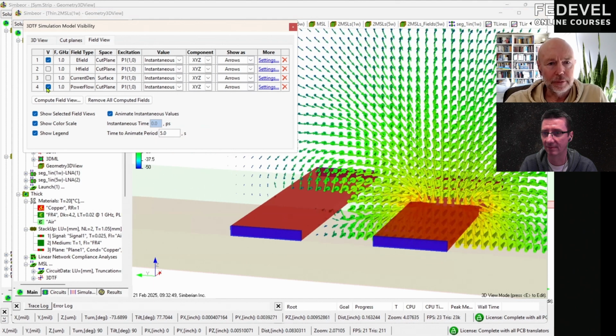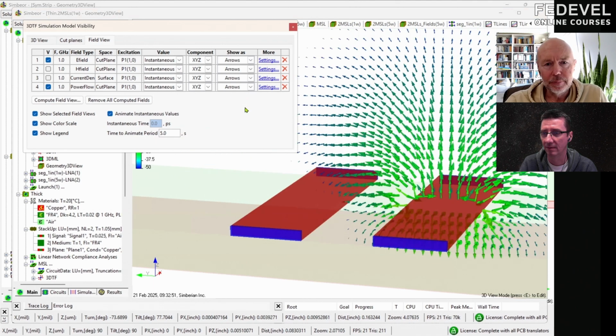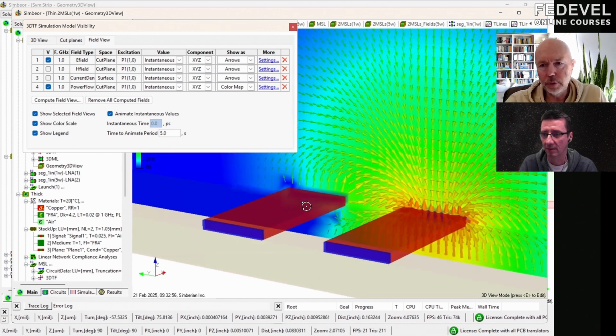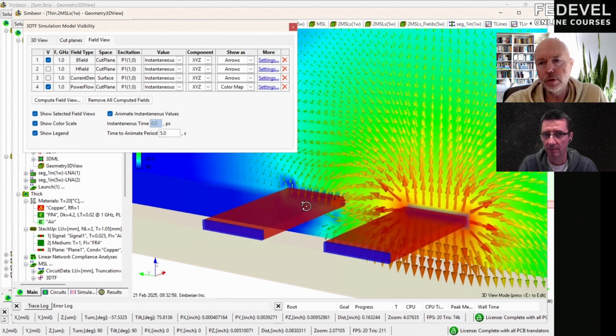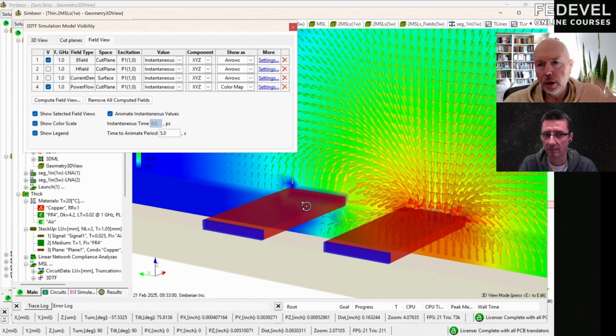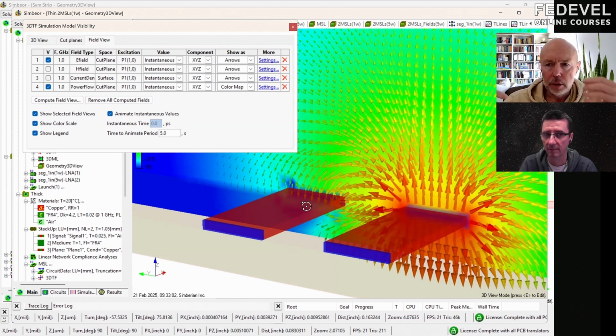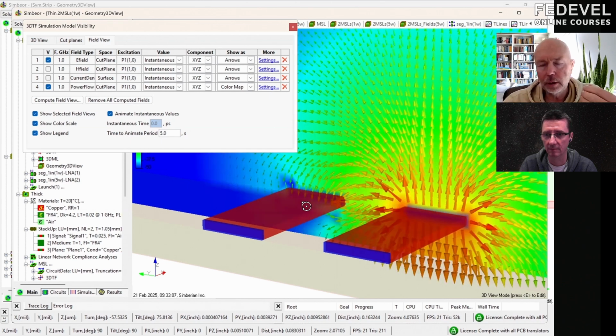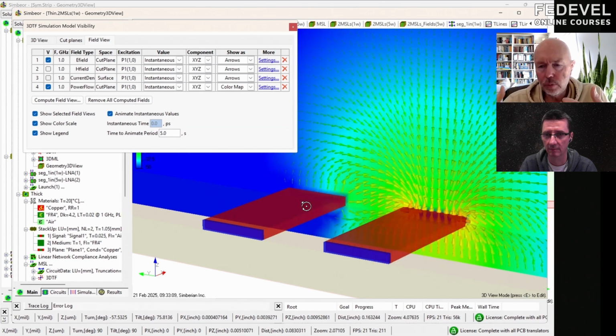That's correct, and that's what is really important to understand in the case of crosstalk. Crosstalk is something that happens around the tracks, right? If you connect two components, there is a driver, receiver, track, and in addition to tracks, there are always reference conductors.